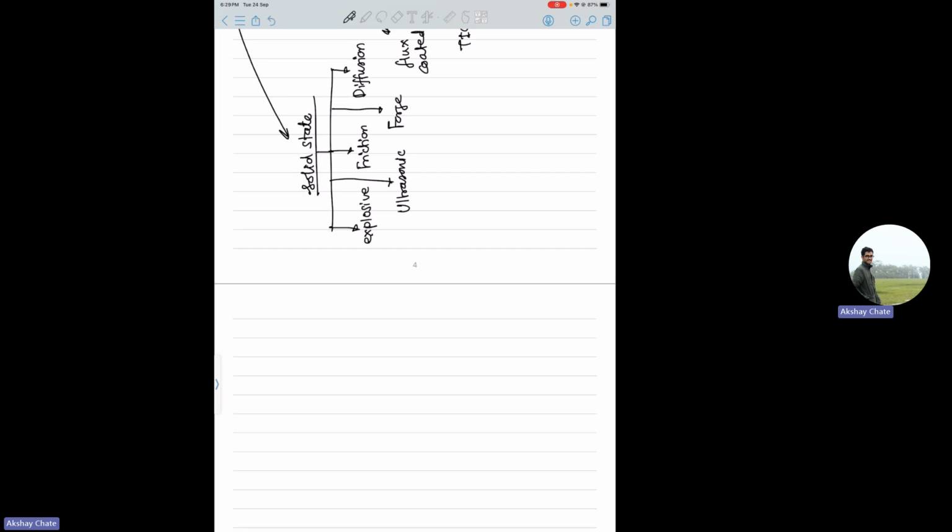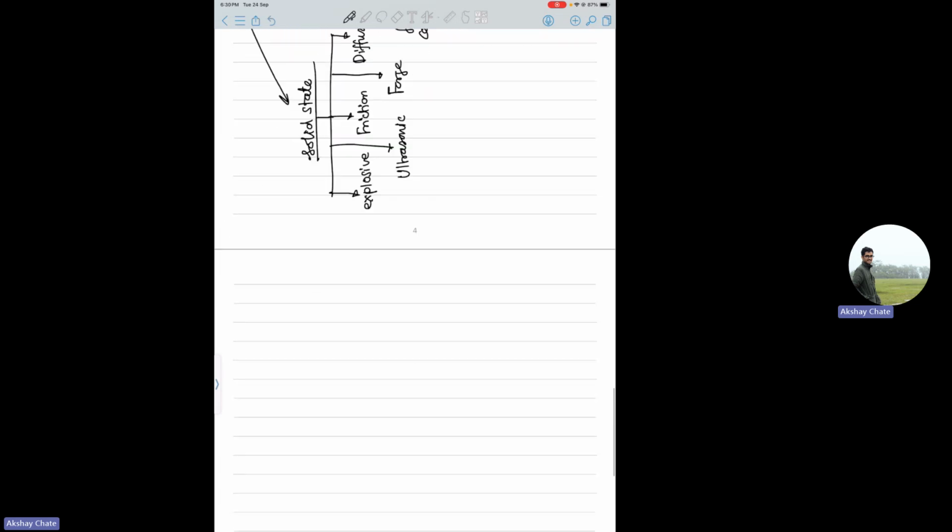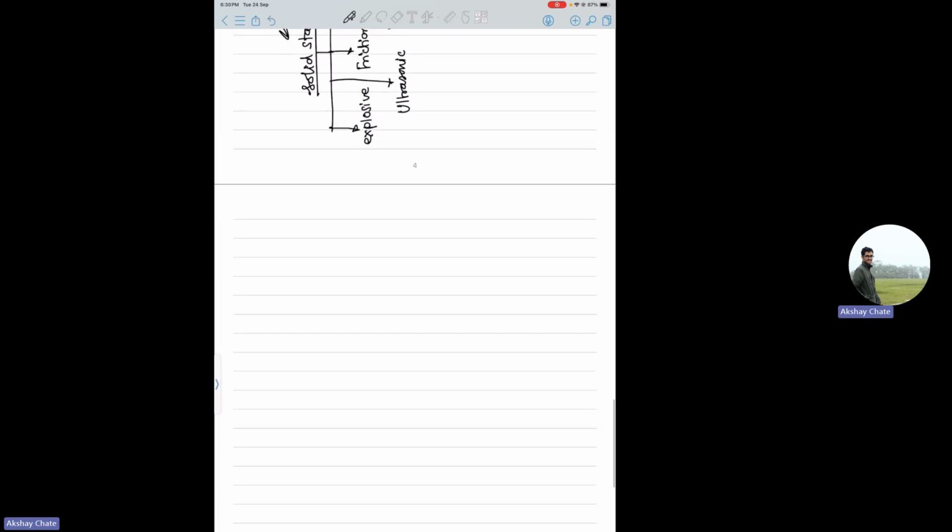Because you'll study different techniques of melting, etc. And these are the conventional ones. Okay, so there are newer or unconventional ones. Usually what happens using these conventional methods, whenever you do welding, you will have a significant heat affected zone, which is not desirable in many applications. Many sensitive applications require homogeneous properties throughout your domain.